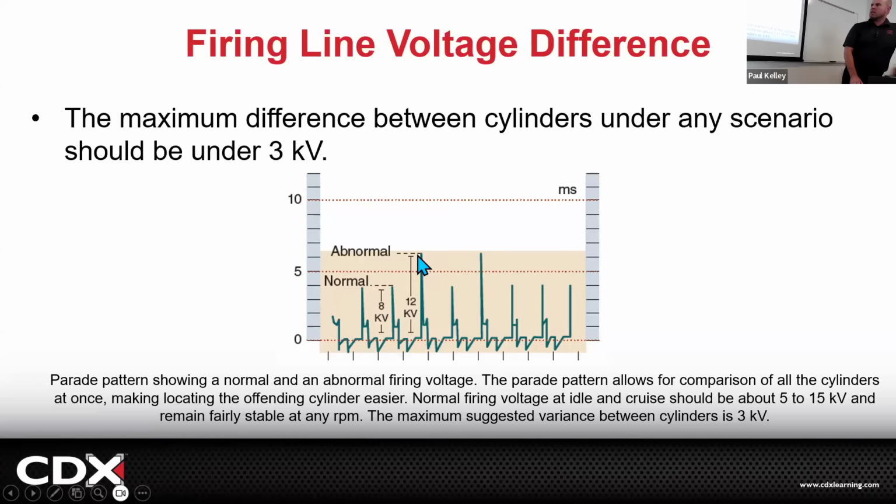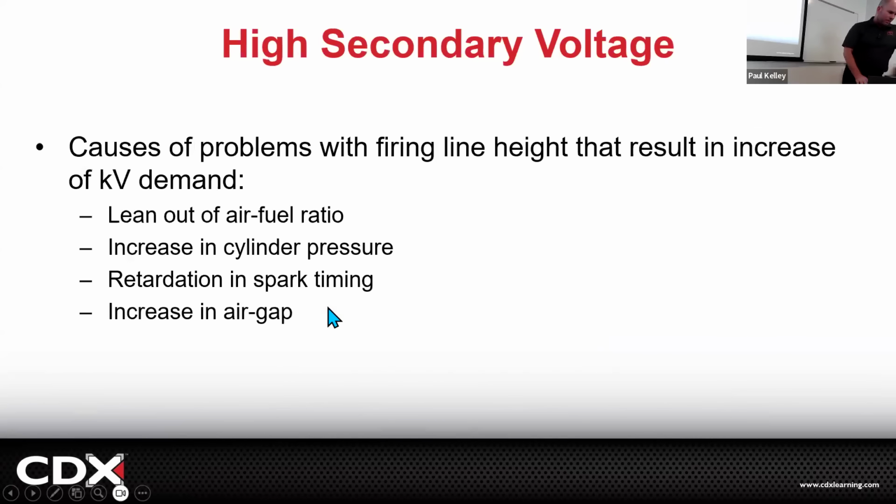So if it's high resistance, maybe you have really high compression, maybe you have corrosion, maybe you have a really big spark plug gap. If it was really low, maybe you have low compression, low resistance, or a really small spark plug gap, right? This can tell you a big story right here. And I typically see 1 or 2 of these questions on the ASE. It's not a lot, but there's something.